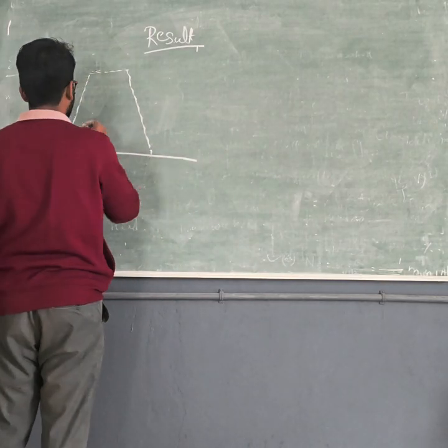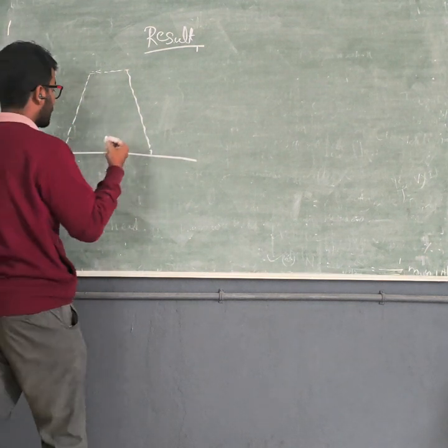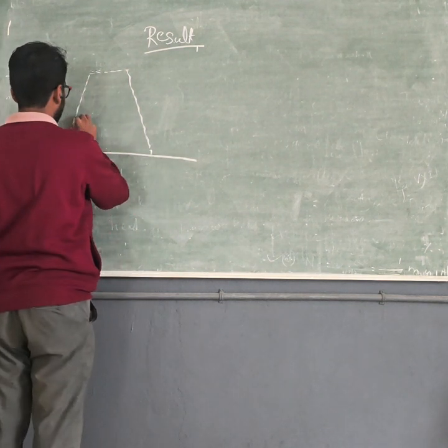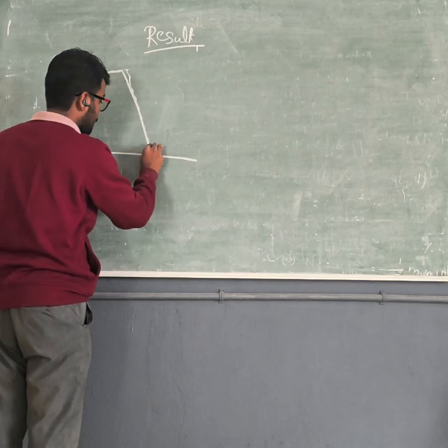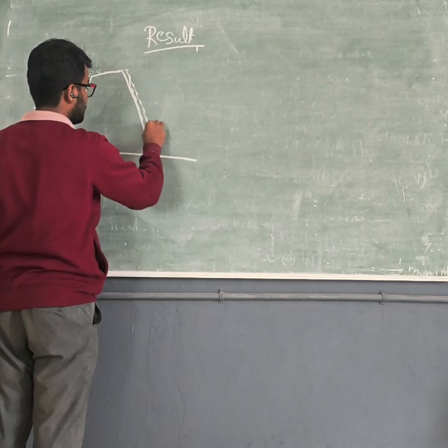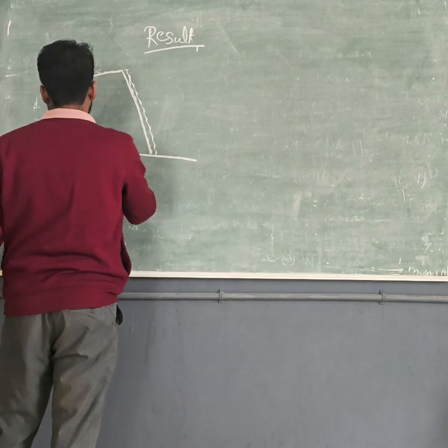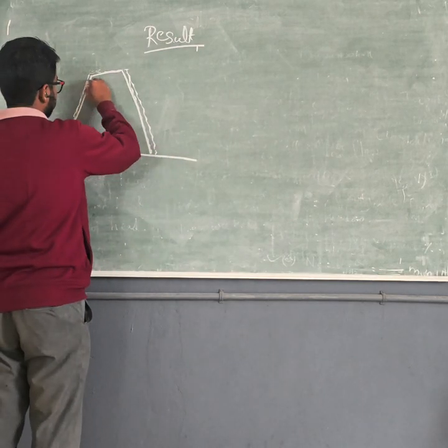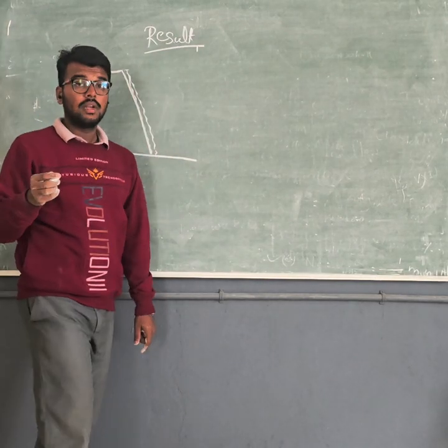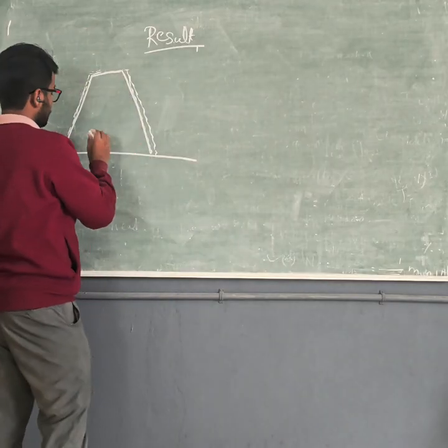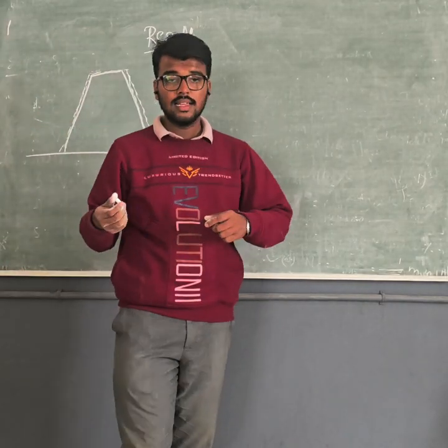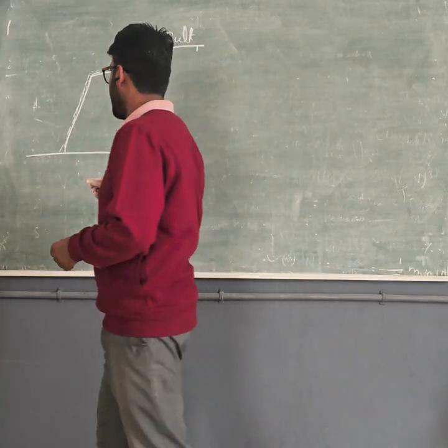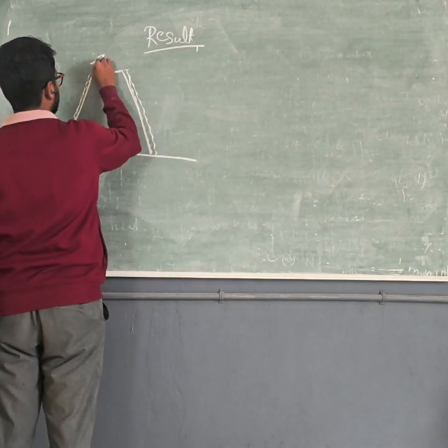If this is the mold, and after removing the mold the concrete stays in the shape of the mold, the concrete gains the conical shape. It is still like the conical shape. There is no shrinkage of the height. We know this one is zero slump.